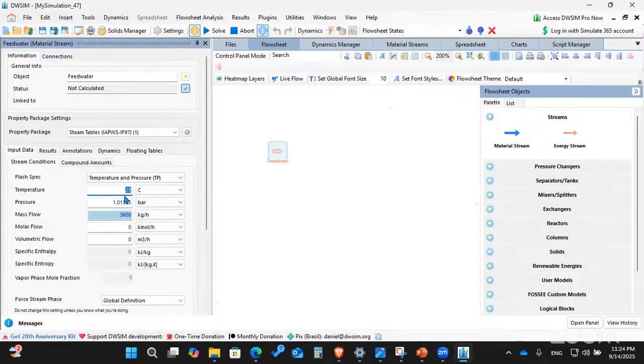So depending on the environment, these are all part of the feed stage during the design concept: the average temperature of the environment throughout the year. This is what you put here. For steady state, we'll choose a static temperature. For dynamic state, it could change to whatever the atmospheric temperature will be. So we are assuming 30 degrees, and we choose 30 degrees and that's it.